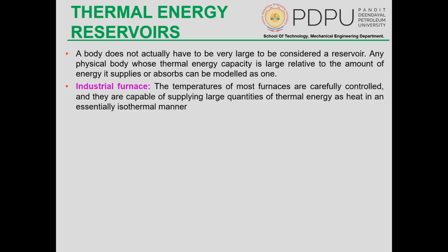Obviously a furnace is not as big as the ocean or atmosphere, but however we see that the furnace is able to supply a large quantity of thermal energy, and that too in an isothermal manner. Isothermal means that the temperature of the furnace is never decreasing. So this can be termed a thermal energy reservoir. Obviously we will have to continuously supply fuel to maintain the temperature of the furnace, but the idea here is that the temperature of this particular source will never be decreasing. Okay, so that is the case.